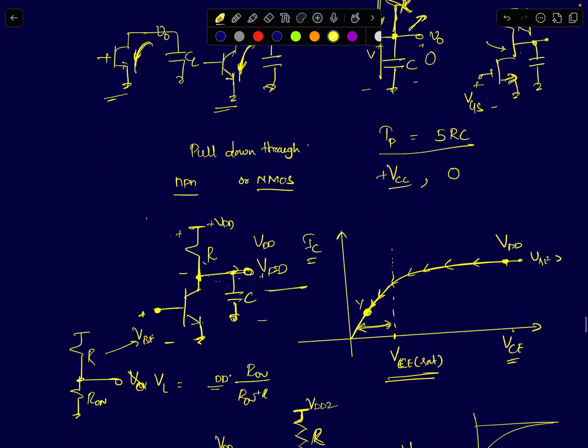One more thing to keep in mind is that the final stage in an open collector or open drain output based comparator will resemble a TTL logic. It's just a common emitter amplifier with a resistive load. For such circuits, for the charging path, this transistor is cut off, so there is no problem. The output node will be charged to VDD volts. But when it comes to discharging this cap, the transistor will try to discharge it. But anytime this node voltage goes lower than VDD, a current will be set up in the resistor, and the resistor will try to charge the output node.